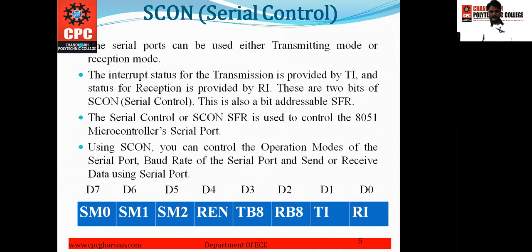These are two bits of SCON, the serial control register. This is also a bit addressable special function register. Bit addressable here means we can change its 8 bits according to the operation. The SCON special function register is used to control the 8051 microcontroller serial port operation. Using SCON, you can control the operation modes of the serial port, the baud rate for serial communication, and send or receive data using the serial port.